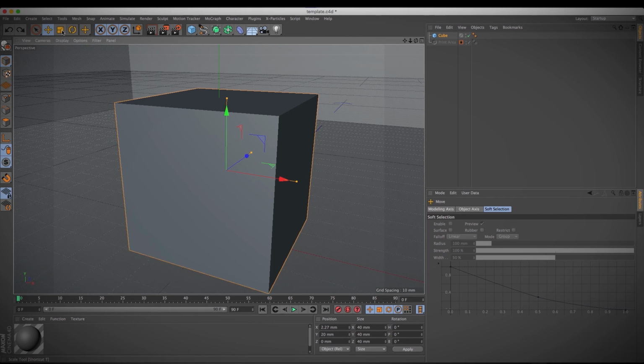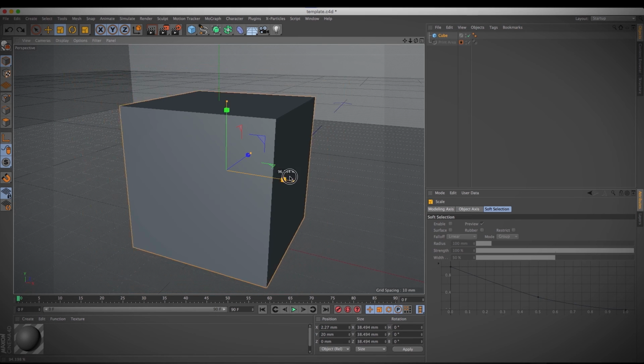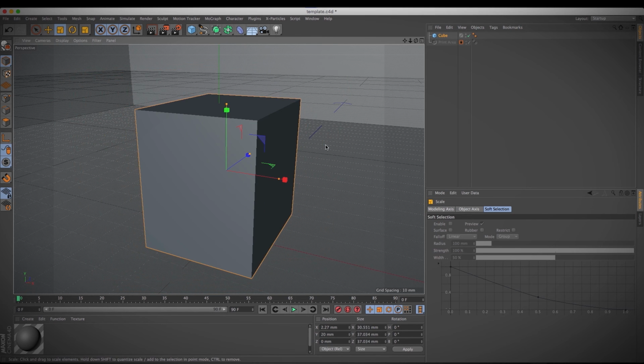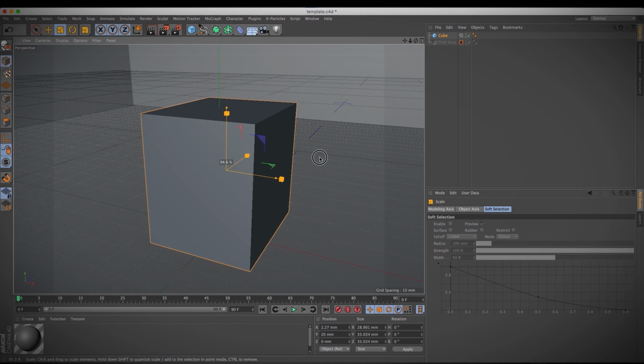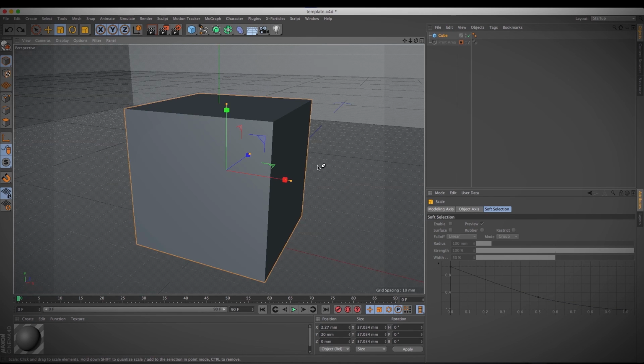Next up is the Transform or Scale tool. Hitting T on your keyboard will access this function. The same applies. If you mouse over a handle, it will scale in that direction only, and in this mode, we scale proportionally along that axis in both directions. If you wish to freeform scale an object, just click outside the object handles and click and drag your mouse to scale in all directions. Again, I don't suggest using this method when modeling, as you will likely want to restrain the movement to an axis. Finally up is the rotation tool.